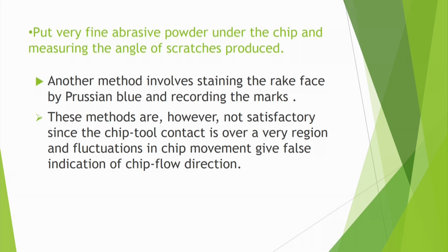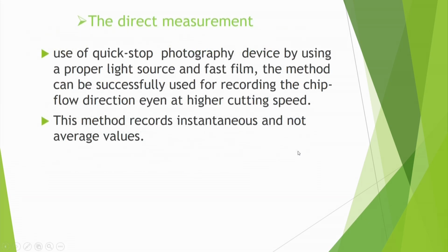These methods are however not satisfactory, since the chip-tool contact is over a very small region, and fluctuations in chip movement give false indications of chip flow direction.